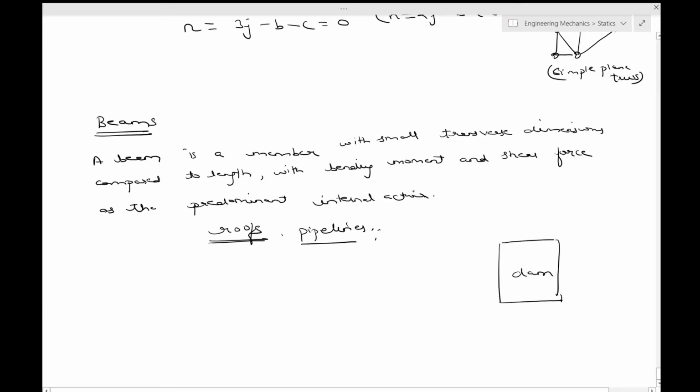Think of it like a dam, which has this as your head, and say it's not allowing any water to flow right now, or allowing very little water to flow, but let's assume that it's stopped now, no discharge of water is over here. Now, as you know, the force which will act on this sort of wall over here, it will be atmospheric, and as you go deeper, it will increase with the depth, like a rho g h sort of behavior.